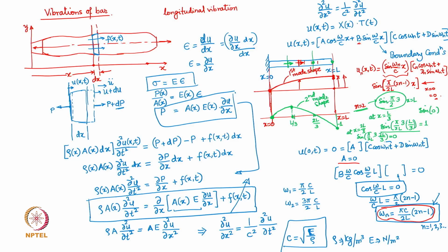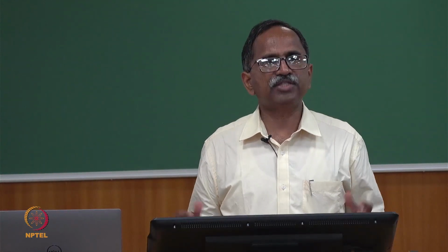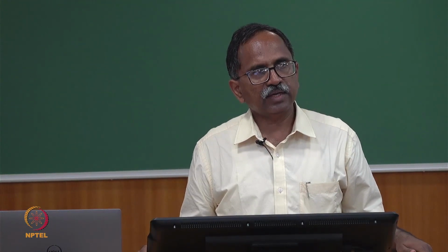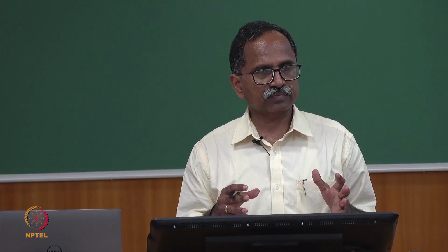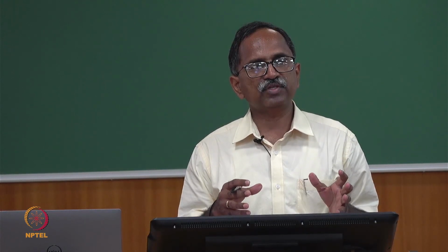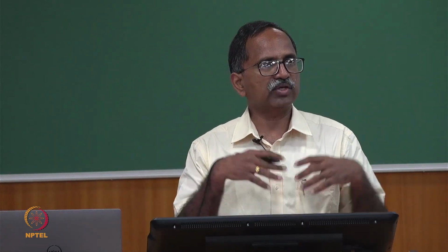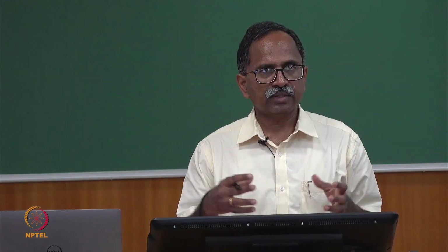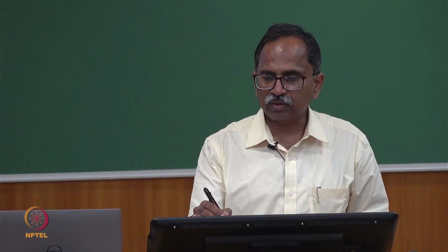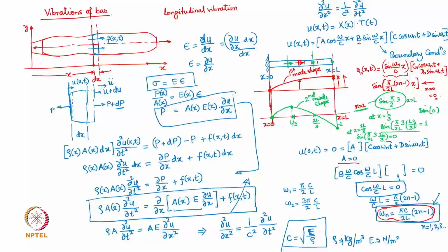Now what is the relevance of these? Knowing the mode shapes in general, I am saying that if I know that this bar is going to vibrate close to its second mode because of the operating conditions, then any mounting on this bar would be preferred to get located here.